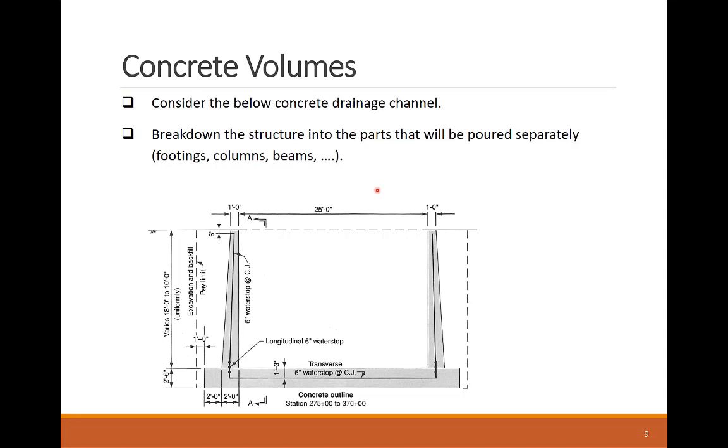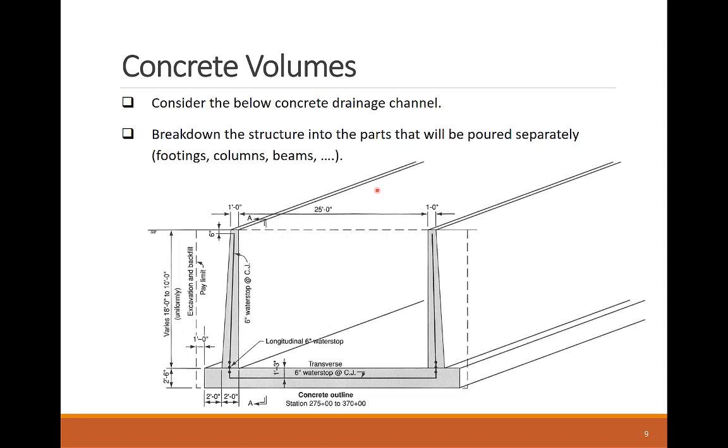Calculating the volumes of concrete depends on visualizing the structure and dealing with its geometry. It's great that most concrete structures are geometry friendly and are composed of simply 3D geometry shapes like cubes and cylinders. The shown cross-section is for a concrete drainage channel. To find the concrete volume, we will need to find from other drawing sheets the third dimension, or the length of the channel, to calculate the volume as the cross-sectional area times the length.